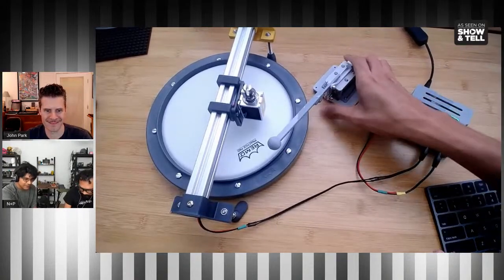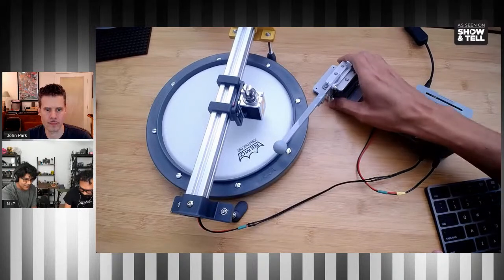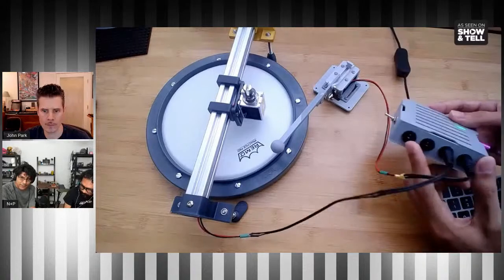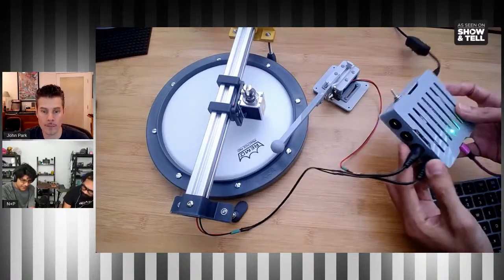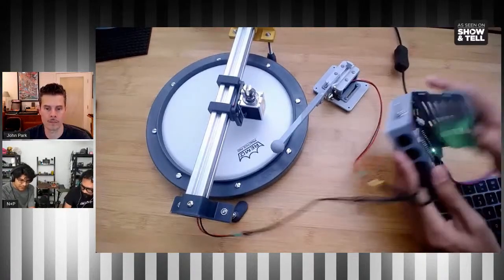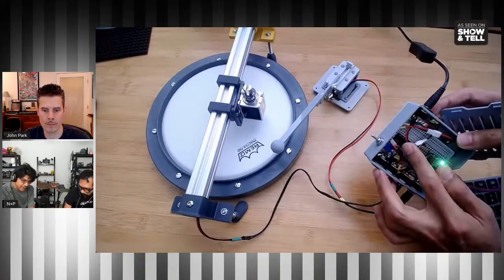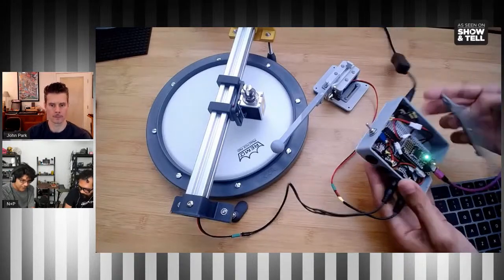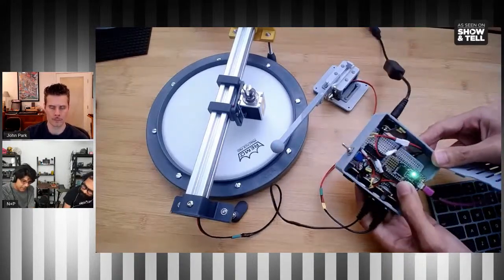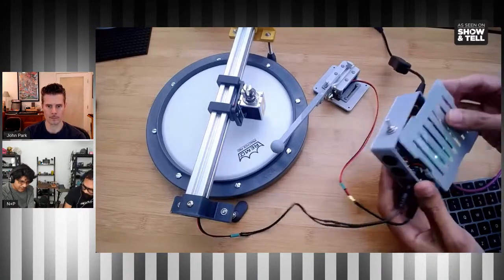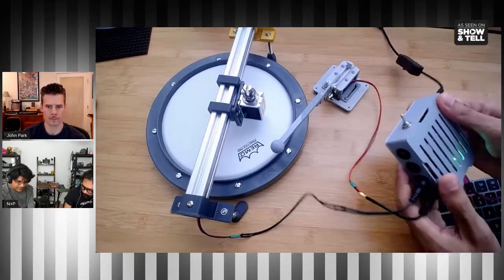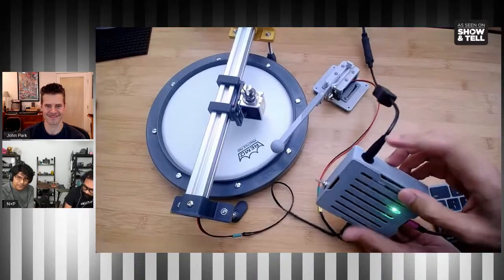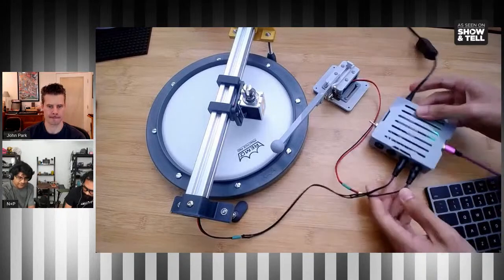The real trick here is setting it up so you're striking the right spot. And yeah, the controller box is right here. It's got that snap fit stuff to it. We have 4 broken out DC jacks, but the Darlington driver has up to 8 inputs, so theoretically we could do 8 different solenoids, but we're doing 4 for now because we want to keep it simple. It's running the Feather M4 with CircuitPython, of course, and this snaps together like that. So you can plug in your things there, and then we have a 12 volt power supply running in here. It's got 5 amps, I think.